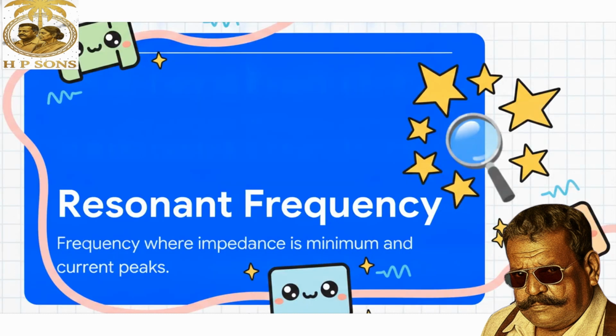Well, it creates a beautiful phenomenon called resonance. When the inductive and capacitive reactances completely cancel, the circuit's overall impedance drops to its absolute minimum. It literally just becomes the value of the resistor. Because opposition is at its lowest possible point, it allows a massive, powerful spike in current amplitude. And this happens at one very specific natural frequency for any given LCR circuit, which is calculated as 1 over the square root of L times C.